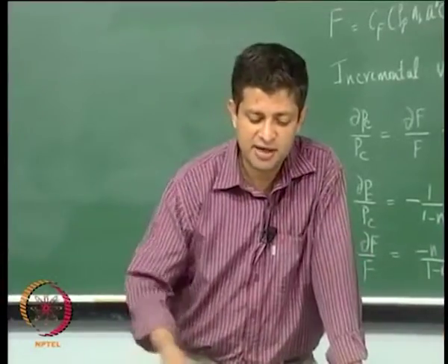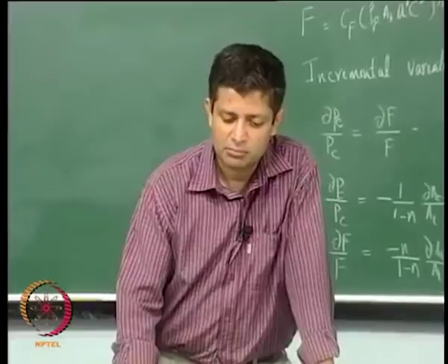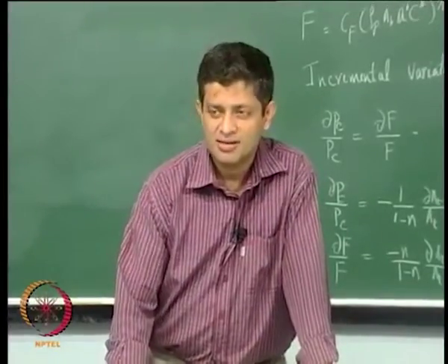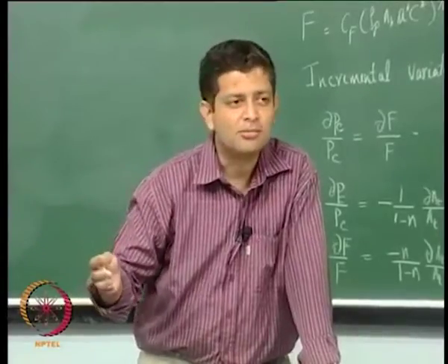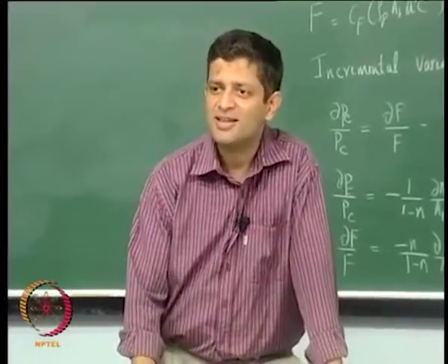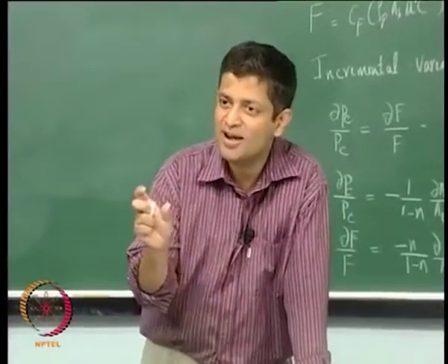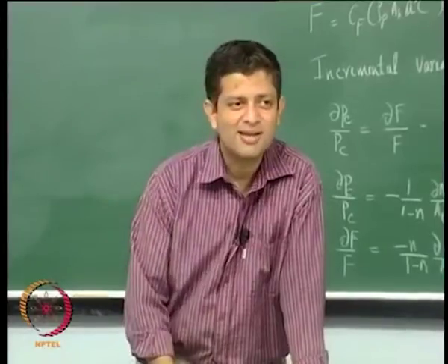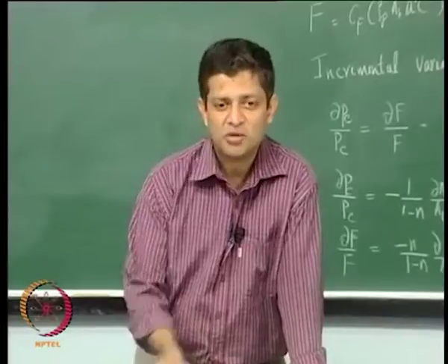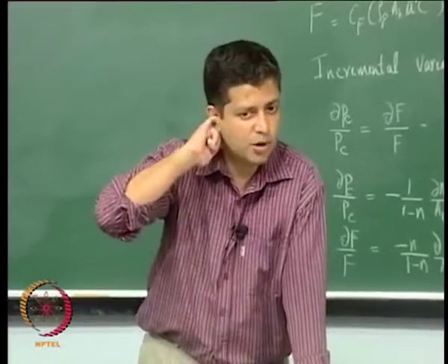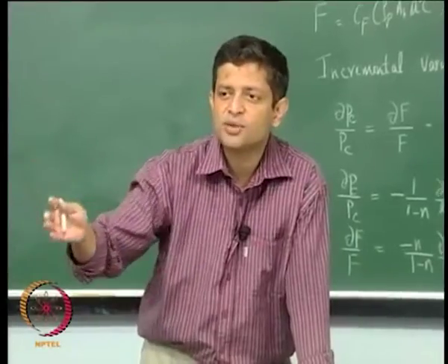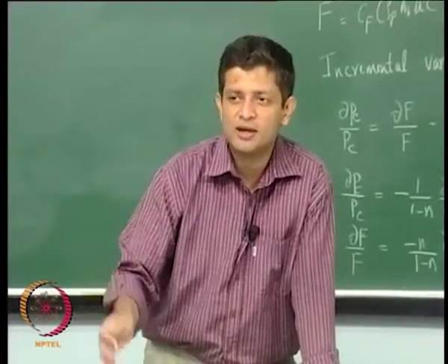And the reason why, in one sense, they make a segmented grain is, let us say you are casting 200 tons in one go. If you make the entire motor and if you realize that the imperfections are only in certain portions, then you have to redo the entire 200 tons. So, it would be better if you can make it in smaller segments, so that you can take out the portion that is bad and then replace only that portion.